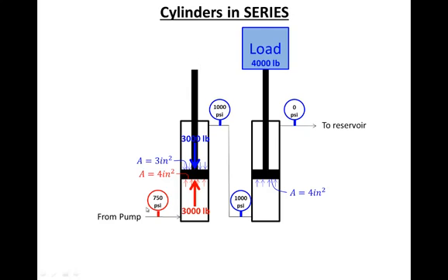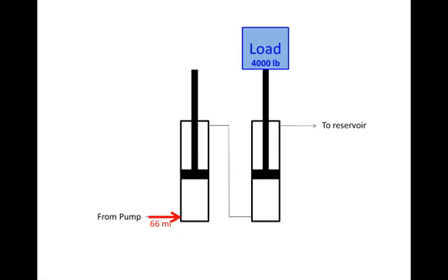It's also interesting to note what's happening across this piston. 750 psi of pressure going in, but 1,000 psi of pressure are coming out. We've essentially used this piston that had no load as a pressure amplifier. Now let's take a look at what happens to the speeds of these cylinders. Before, we noticed when the load was here, this one would move faster and further. Is that still the case when the load is here?